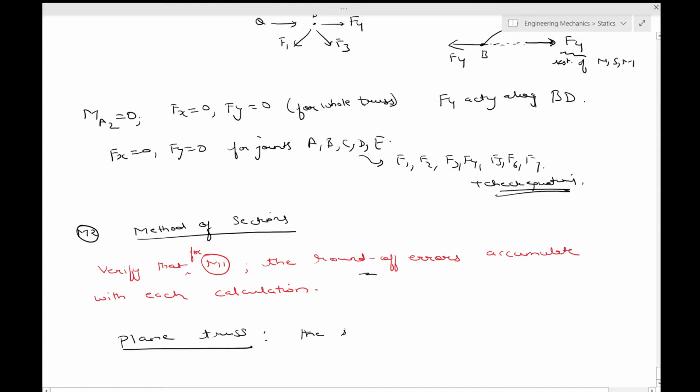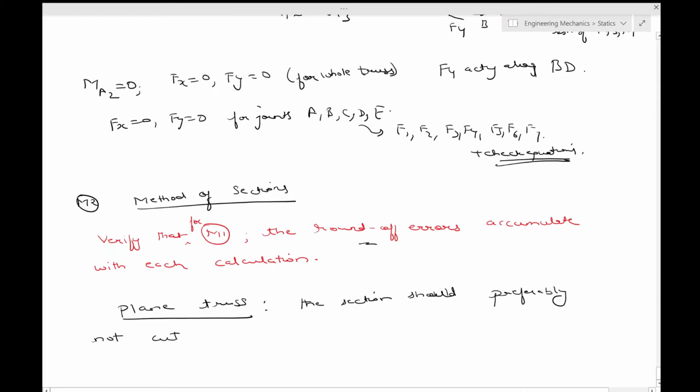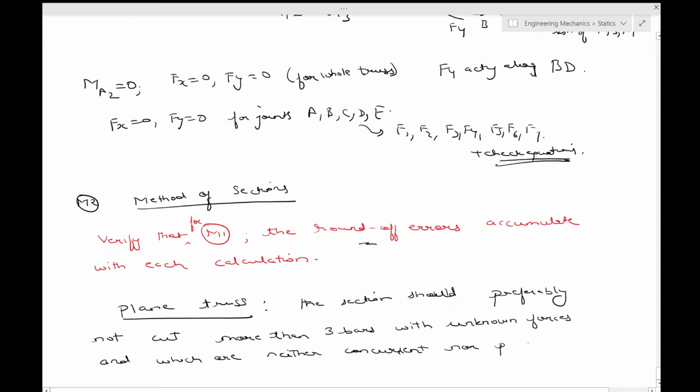The section should preferably not cut more than 3 bars with unknown forces, which are neither concurrent nor parallel. Okay.